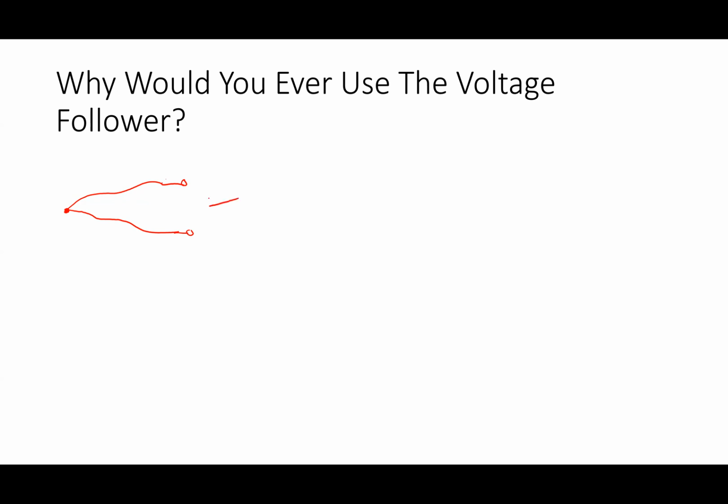But looking into the terminals here, what do I have? Well, I got two pieces of wire. Somehow there's going to be a voltage at those two pieces of wire. But if I got two pieces of wire, what must I also have here? Resistance. So I have a Thevenin equivalent looking into there, right? Basically, it would look like this. Electrically, looking into those terminals, that device on the left, what I have is a voltage source in series with some resistance, okay?